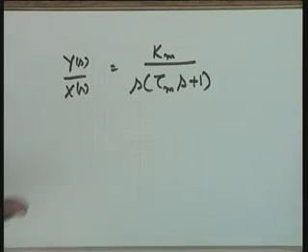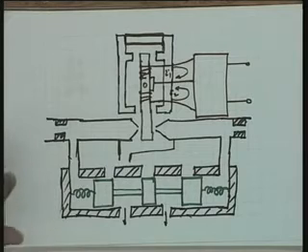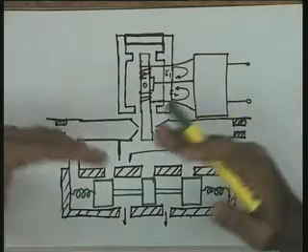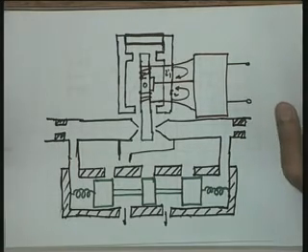But before that, one more device I have to give you, so that the total system can be explained to you, and that device is an electro-hydraulic valve. This device, I need your attention on this. This is an electro-hydraulic valve. Now what is this valve and what is the purpose of this? As you will see once you understand this particular device, the electro-hydraulic valve is a very useful interface between an electronic controller and a hydraulic actuator.